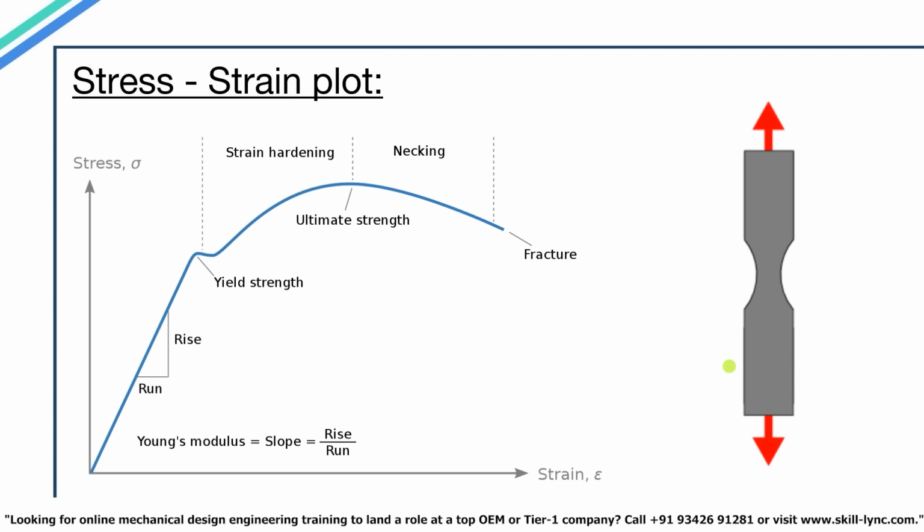So the way this works is, if you want a stress-strain graph for steel, then a steel rod will be selected and it will be subjected to tension loads to increase the stress of the steel rod. And they will keep increasing the stress value till the material breaks, and during the process a device will be used to keep track of the strain values in the rod. Then using all the stress and strain values, the graph is plotted. Now you might wonder, why do we need these plots?